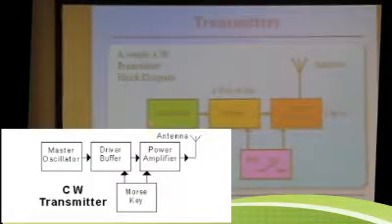So you have an oscillator that's set up at the milliwatt level. You see the MW there. So it's making just very, very low power frequency. Then we've got a driver. The driver bumps it up to a few watts. And then we turn the driver on and off. And we've got a power amplifier that gets us up to 100 watts, then goes out to the antenna.